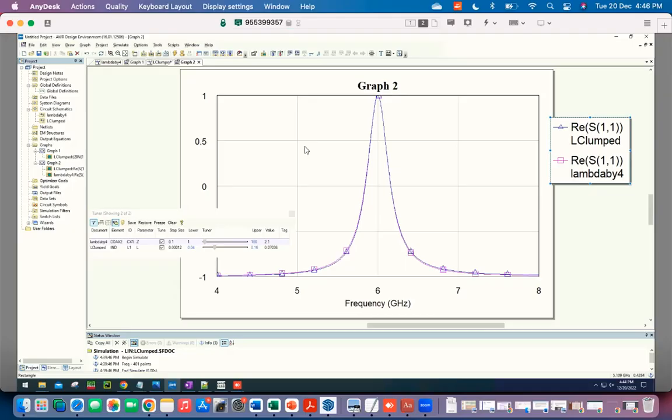You can almost think of this as that the only kind of transmission line which might come close to it is really 2 parallel plates, which are very close to each other, so that you can get a high specific capacitance. Anything which is planar, where the capacitance is sort of coming by proximity and field lines going through the dielectric, is never going to give you anything in this range. In fact, it's sort of a rule of thumb that anything less than 20 ohms and anything greater than 90 or 100 ohms is not a practical design.